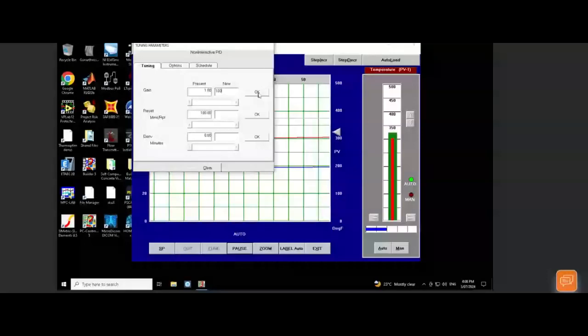Can you see that this is getting bigger and bigger and bigger, the actual process variable. So obviously the trick is to avoid that by keeping your gain as low as possible. But if your gain is too low, it means that your process variable doesn't follow your change in your set point quickly enough.